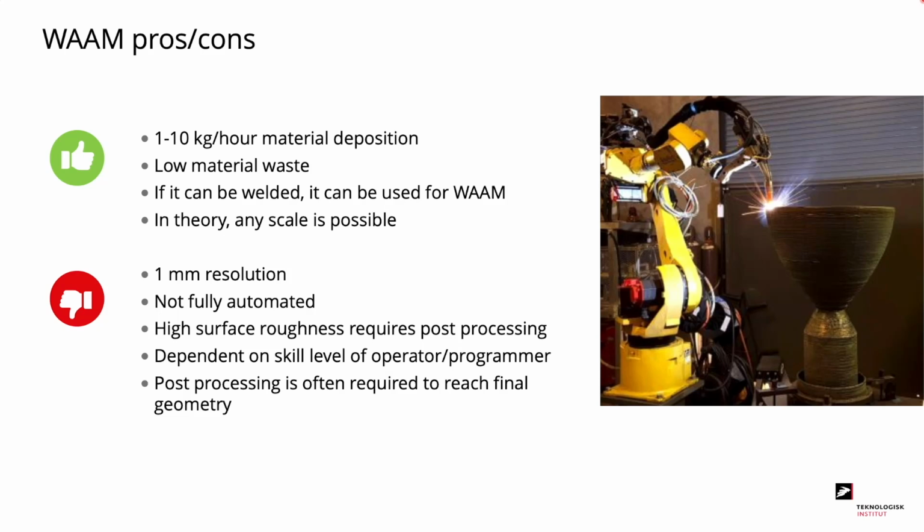In theory, any scale is possible and you can set it up anywhere. Some of the disadvantages are that we have only 1 millimeter resolution. It is not a fully automated process, and you will have high surface roughness of as-built parts, which requires post-processing. The outcome of your process is highly dependent on the skill of your operator and programmer, and in general, you will be needing post-processing to reach your final geometry.